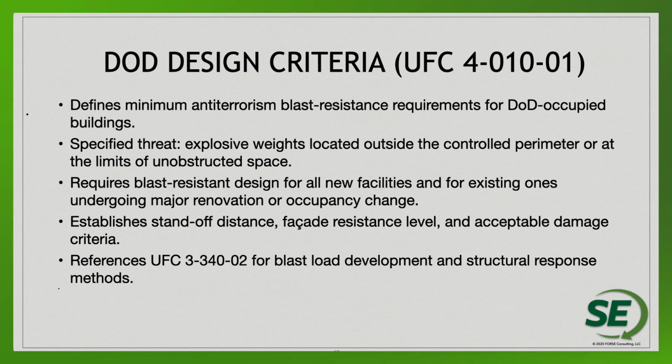So DoD's minimum design criteria provides a baseline anti-terrorism requirement for all DoD buildings. It defines minimum standoffs and different acceptable damages here. These requirements are based on a baseline external explosive threat, and they reference the UFC 3-340-02 for explicit blast design.